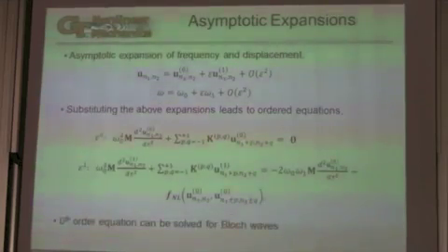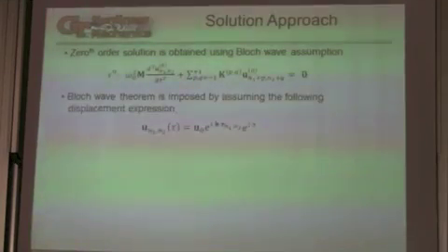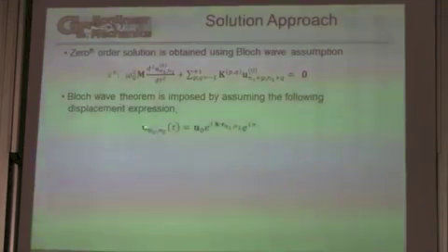Okay. All right, so zeroth order we solve for Bloch waves. Francesco actually asked me, where are the plane waves? Well, here's where the plane waves are. Here are the unit cell degrees of freedom, which is of course a vector. So we have a wave mode, much like in modal analysis and vibrations. In fact, we'll have n of these. If we have n degrees of freedom, we get n dispersion curves, and we have n of these modes.